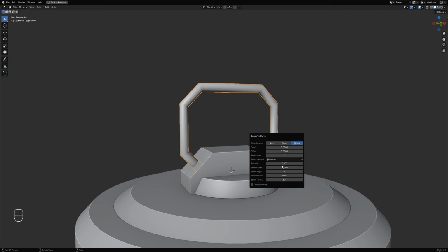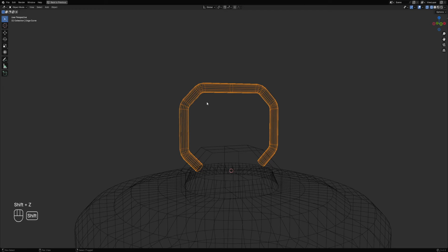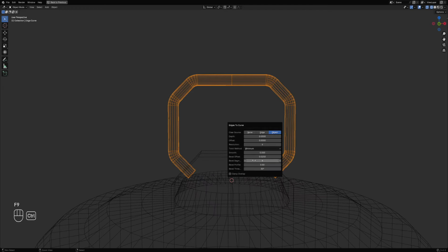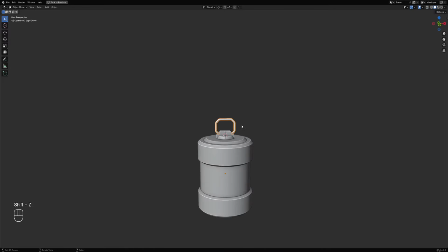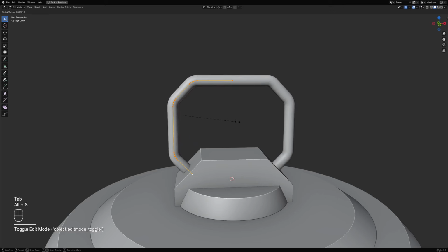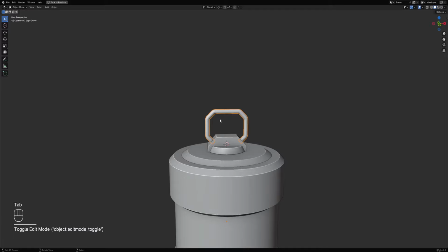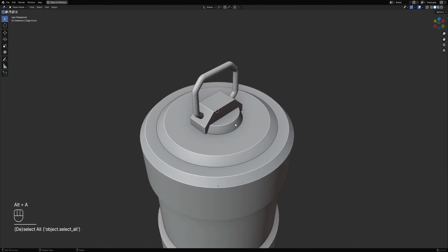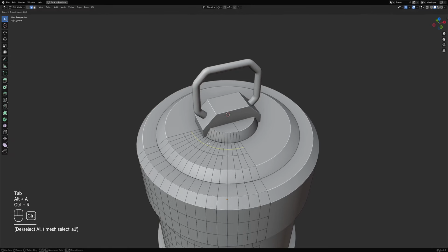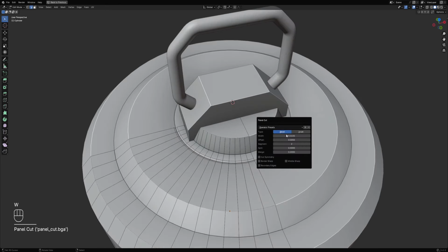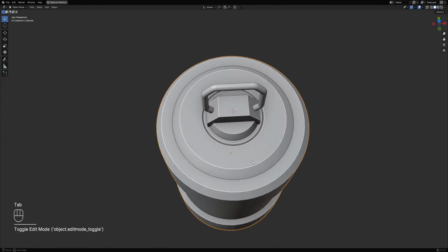And we can bevel offset, and let's look at the wireframe. Something like 4 segments. Yeah. So you can affect the curve object in edit mode. You can use Alt S to affect the width or thickness of the curve. Okay. 0.015, 0.015. Sharpen the edges.